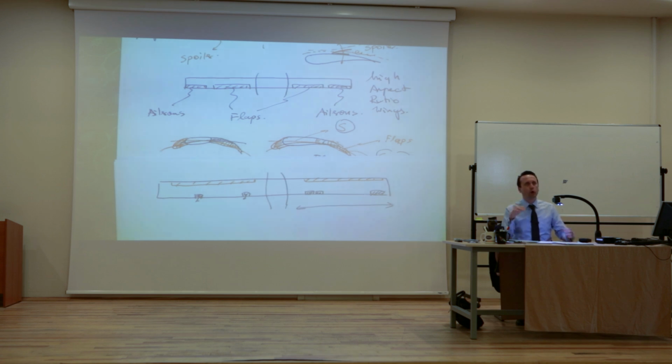Now the control on the horizontal tail must have enough power to adjust for everything. When you design your aircraft and you have a moment coming from these things, and you don't have enough moment from the horizontal tail, then you can't fly the airplane. As flight mechanics engineers, you have to make sure that whatever moment is created from these things, you are able to adjust it or trim it with your horizontal tail. Because if you cannot trim it, then you have a problem.